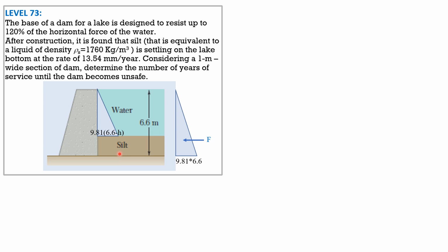Then by Pascal's law, we have to transmit the pressure. So rectangular, then we have a pressure diagram here, which is triangular. And this is equal to the specific weight of silt, 1.76 times 9.81 times the thickness of silt, which is H. So call that F1, this one for the equivalent rectangular pressure diagram F2, and for this triangular one in the silt portion F3.